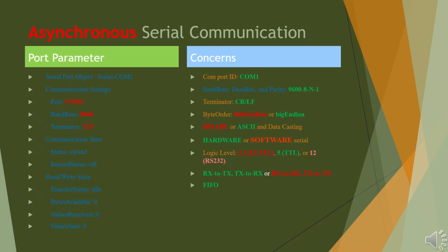Finally, many UART systems include a FIFO, first in, first out, buffer to temporarily store incoming or outgoing bytes. This buffer helps prevent data loss when the processor is busy with other tasks, improving communication stability in high-speed or multitasking systems. In summary, serial communication might look simple, just a few wires, but behind it are many small details that must be set correctly. Baud rate, format, voltage, and wiring all need to match precisely for your data to be transmitted cleanly and consistently.